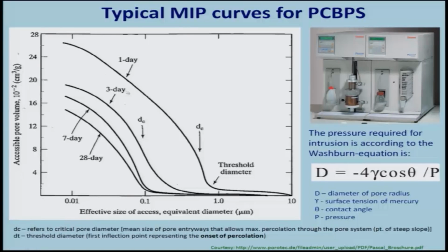So, how is it determined and why is it required? When the mercury enters the pores of the sample, you see that the pores are not just one size, they are distributed. So, typically in this curve what you find is that the pores are between 0.01 micrometer to say 1 micrometer, and hence in order to characterize this curve by just one size, the value DC is used.